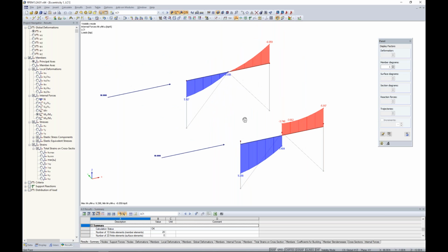Well, you'll notice the drastic difference with the strong axis bending. In my first example, we transition here from a positive moment, 0 moment at the midspan, into a negative moment. Quite a different story when we've taken into consideration that eccentricity. So we have a huge jump in the moment where those chevron braces are framing in. And we know that this really just is not ideal behavior.